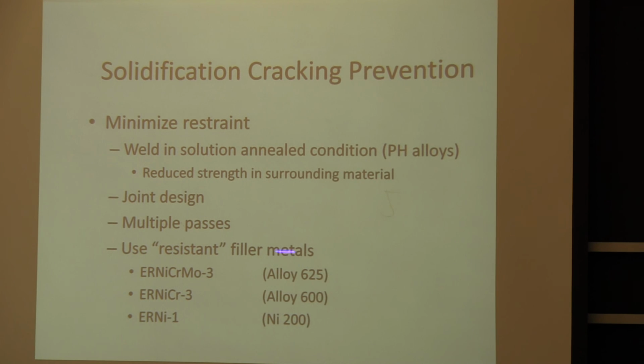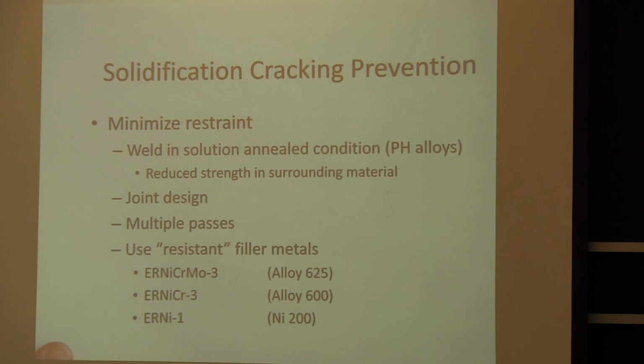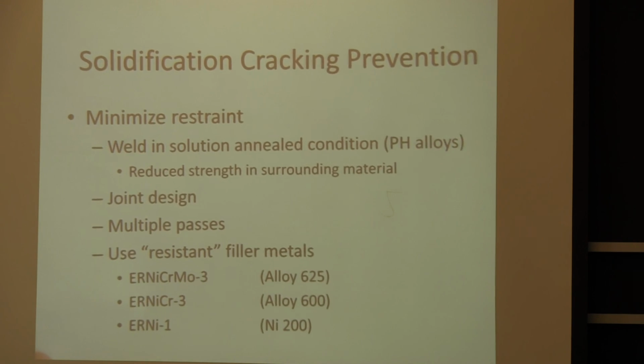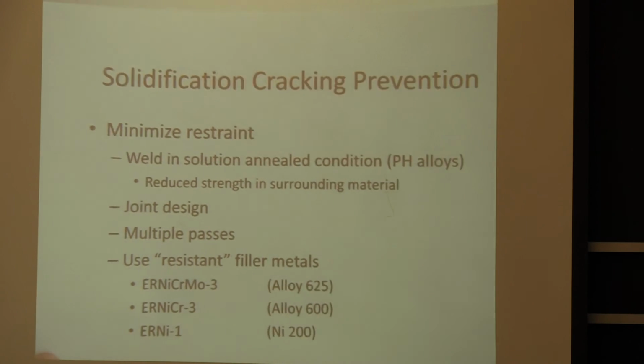But some of these alloys here are solid solution strengthened alloys, and this is a pure nickel alloy. You get less of that strengthening and hardening going on in the weld, which leads to lower restraint and less solidification cracking susceptibility.